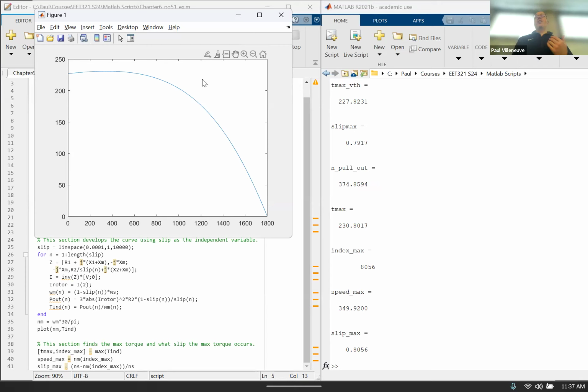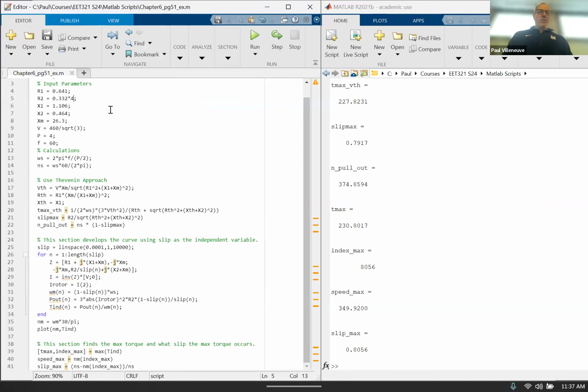Which, again, if you have a lot of mechanical load initially, you might need to run an application like this. But you'll also remember where our power here is outputting the full load, the equivalent of 25 horsepower. Now, instead of being at 1780, now you're at 1728. So you're going to have a less efficient operation. So that's what the wound rotor stuff does for us.